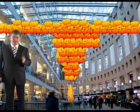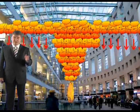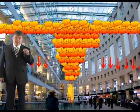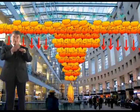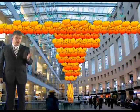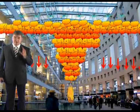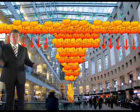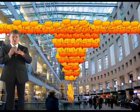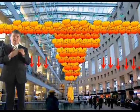However, if sprinklers are installed in the atrium itself, then sprinkler operation will lead to increased heat loss, reducing the buoyancy of the smoke which is coming up, which in turn can contribute to progressive loss of visibility under the smoke layer. So if the sprinkler goes off in the atrium, it's going to start to cool the buoyant gases and they're possibly going to start to drop. However, gases hot enough to set off sprinklers will initially remain as a thermal buoyant layer under the ceiling. In other words, for a general sprinkler head, 68 degrees. If that hot smoke is at 68 degrees and the sprinkler goes off, even with any local cooling, it's still going to maintain buoyancy to get out.